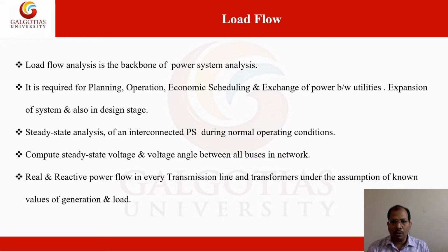Suppose you want to go for the expansion of the network. You can perform the load flow analysis on the network. It is also applicable for the steady state analysis of an interconnected power system during normal operating conditions. Using this analysis, we can compute the steady state voltage and voltage angle of all buses in the network. Actually, using load flow, we are trying to calculate each bus voltage magnitude as well as angle, meaning the phasor value of the bus voltage.